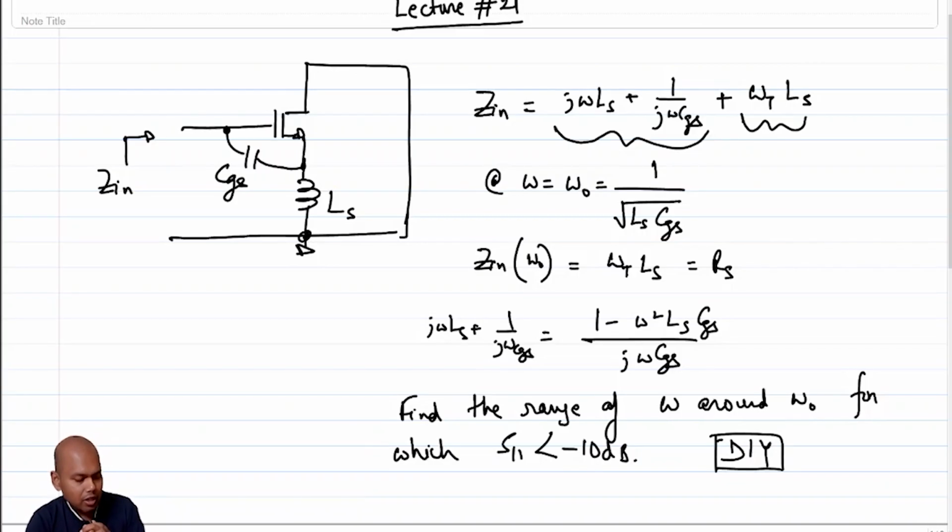Now, without getting into all these design constraints, the key problem here is that the single variable LS is setting both the real part and also the resonant frequency. In any design, you would like to have design handles which are responsible for setting one particular property, not everything else, right? If one design handle sets 3 or 4 parameters, then it becomes very difficult to optimize anything.